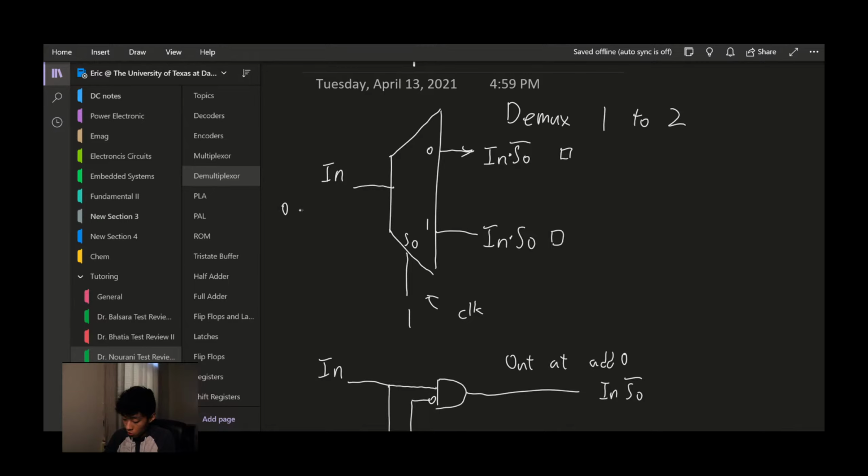So when the serial input comes in, based on the serial input here, we will be able to determine the pixel to turn on and turn off. And usually the clock frequency is really high, so you will not be able to see the pixel turning on and off. You will be able to see that the pixels are always on and changing the value.